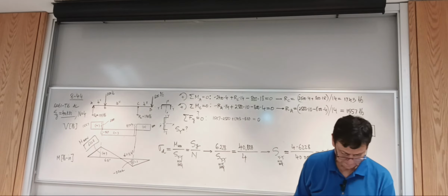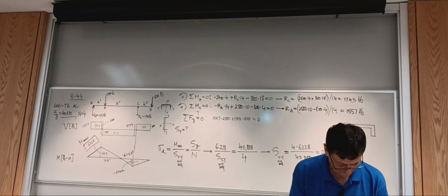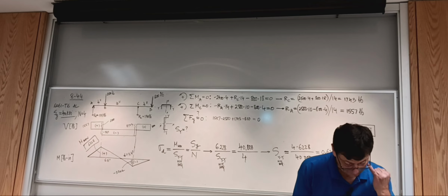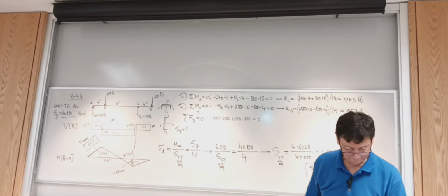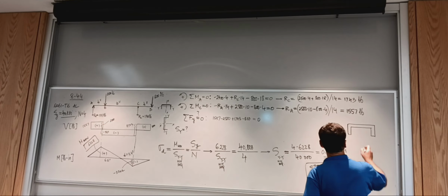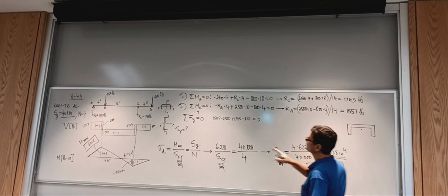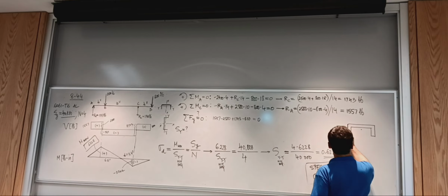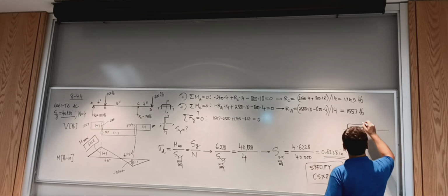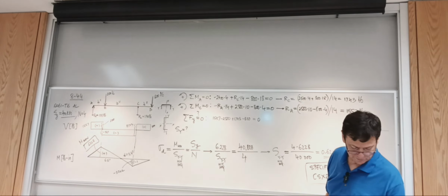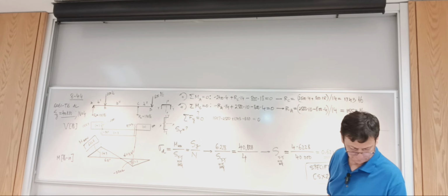So the way out is to calculate the actual first moment of area. So we need to calculate first moment of area. I have the centroid, and there is information in the table. I haven't contemplated the problem all the way to the end, but we can take care of it. So there's no approximate formula given. We use the general shear formula.